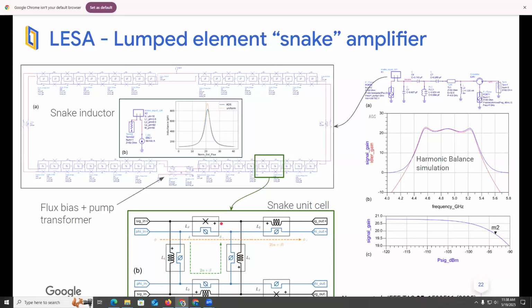Basically, we have two coupled circuits here. We have the electrical circuit in black. We have the phase or flux circuit in blue. We're going to constrain the flux in each of these loops to be quantized. And also because this large array connects in the end over itself, we're going to have to essentially constrain the flux over the whole array as well. So this is kind of what the unit cell looks like.